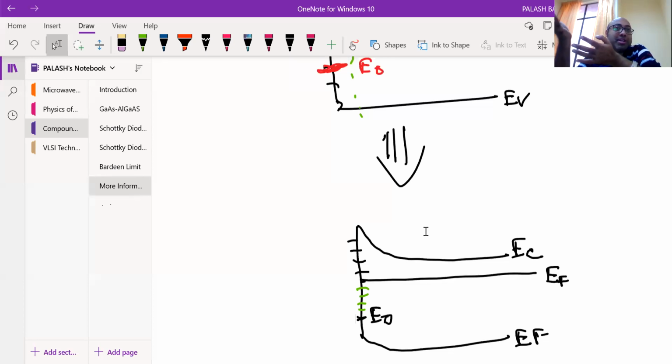So whatever you do, the semiconductor cannot see anything about metal. Semiconductor cannot see metal; it sees only interface states. And the interface states and semiconductor are saying that we have already shared the electrons. Fine. Now in this case, even if we apply voltage, the same thing will happen. You are expecting a current flow between your metal and semiconductor, but nothing will happen because the semiconductor cannot see the metal, so there won't be any current flow. That means your Fermi level is pinned over here. This is called the Fermi-level pinning effect.